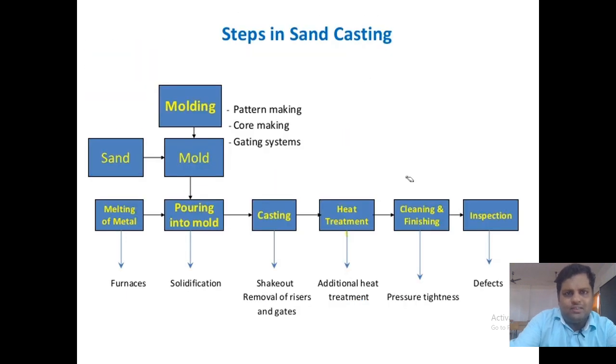Next topic is the steps that are involved in sand casting. You need to know what is sand, what is casting, and what is molding. Okay, I will tell you in the next slide. Before that, we will see the steps involved in sand casting. We will be pouring the sand into a particular mold box, and we will be ramming the sand by keeping the required mold under the sand. Okay, the required mold pattern will be obtained on the sand by ramming it.